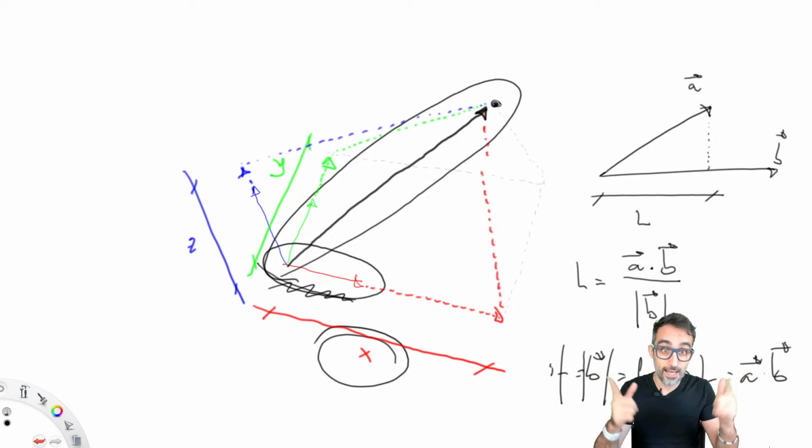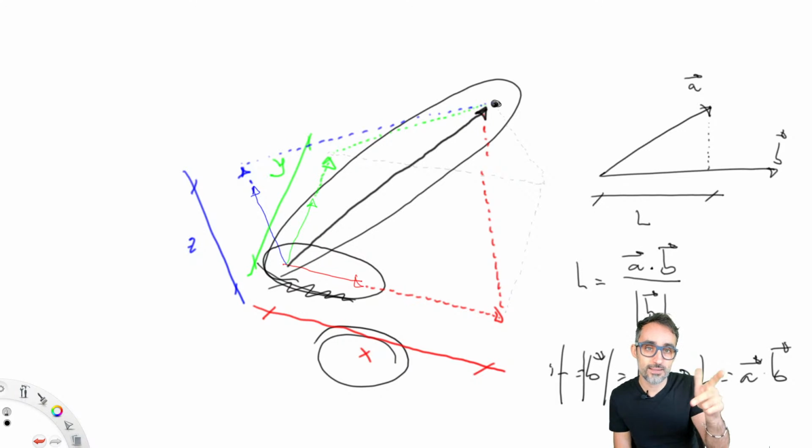You want to take a look at how that is done? It depends on the system that you're using. It depends on the framework that you're using. You will have to choose a form of representing this 3-dimensional coordinate system. In most computational geometry environments, that would typically be represented as a 4x4 matrix with 3 vectors representing the x, y, z directions and another vector representing the position.